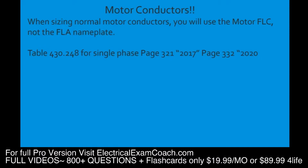So the first thing that we do when we get to this table is we read the black bold heading. It says full load current in amperes for single phase alternating current motors. Great, I feel like we're in the right table. I would go ahead and take a moment, if you can, and highlight where it says full load current, and then highlight the words single phase.